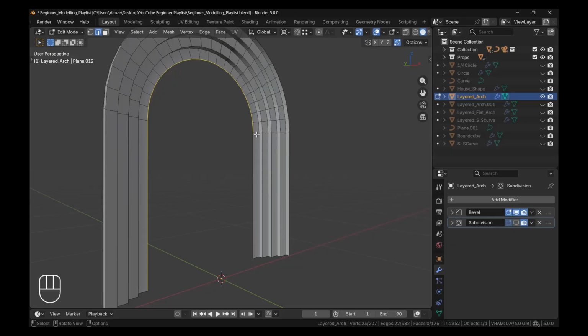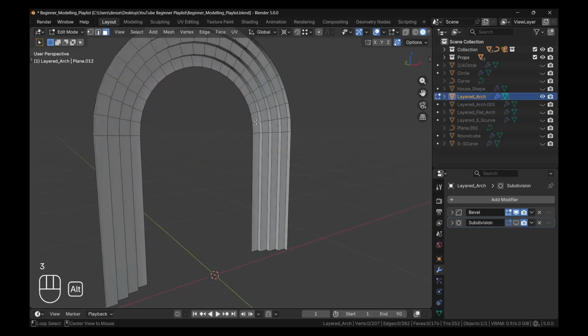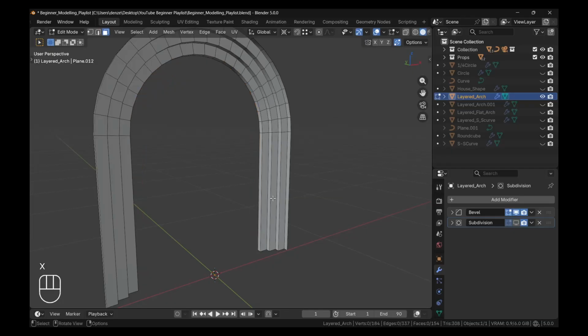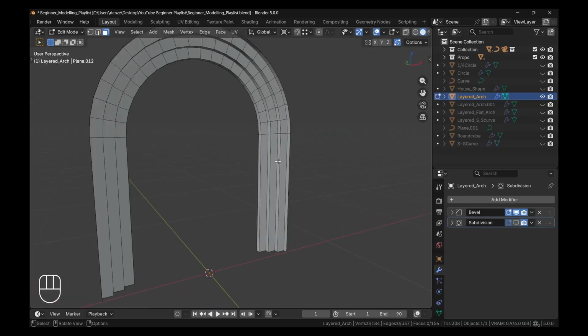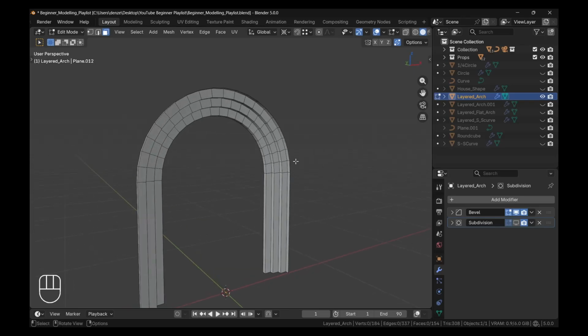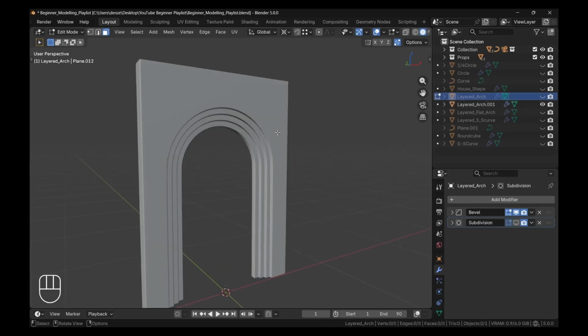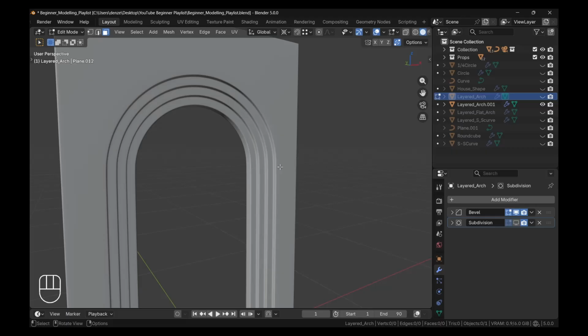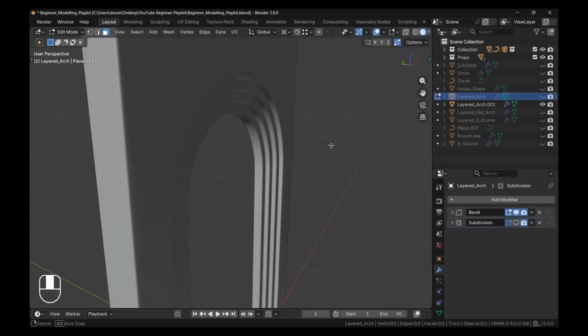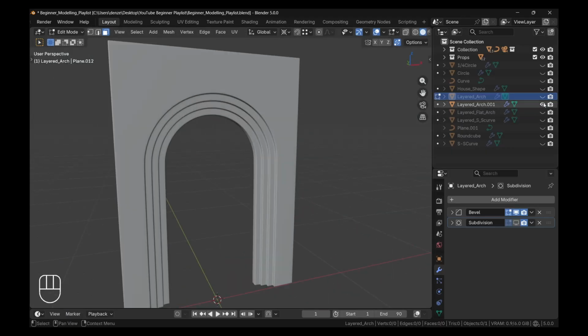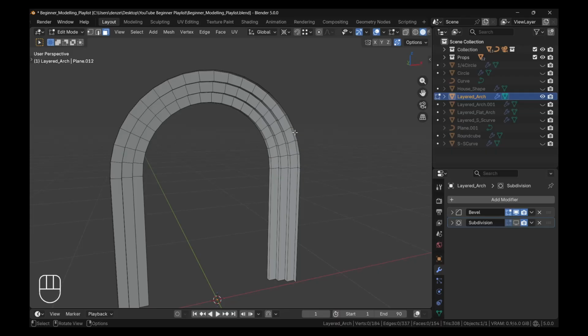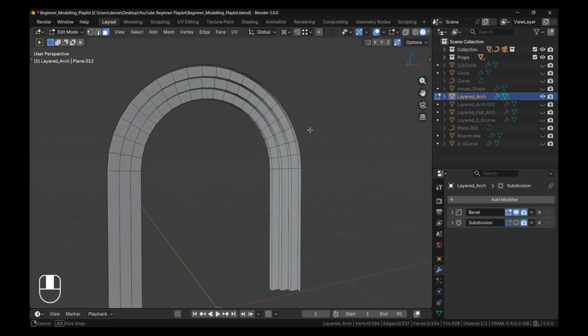Let's delete this face. So press 3 for face select, Alt and left click on any one of these edges here. Select that whole face and press X, delete faces. Okay, good. So we want to create this arch, where we need this face to extend here and also to the back as well. So that's what we're going to do here. So how do we do that? In edge mode, click on this and Alt left click on this edge.